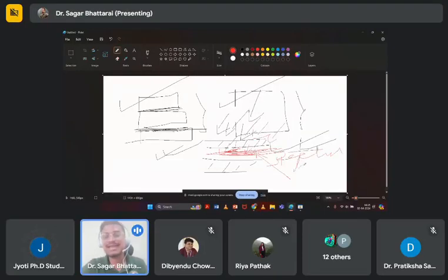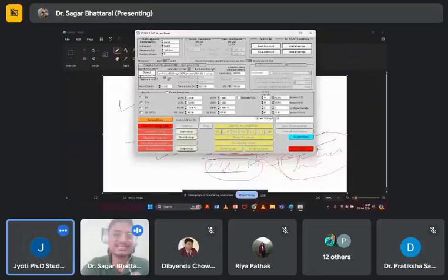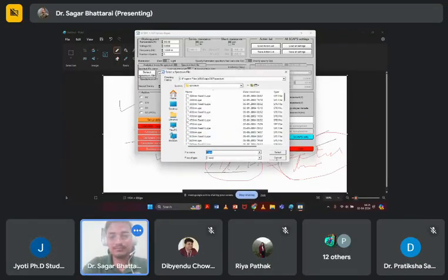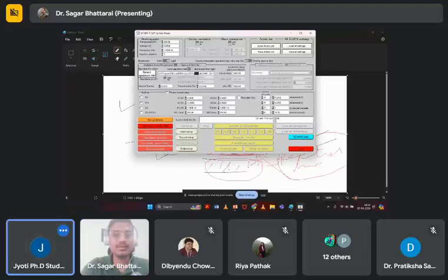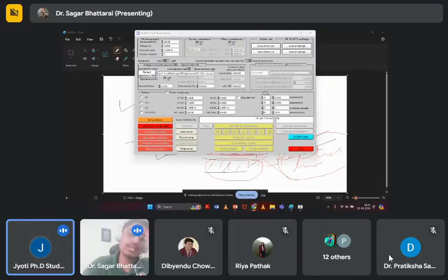So what you do is propose this particular transmitted photon as the spectral line, to specify how much is going through. For that, the option of a spectral file is given to check on the bottom cell. But for practical perovskite or CIGS based simulation, you don't need to do anything. Just choose 1.5. Already it will be chosen. You don't need to worry about that.